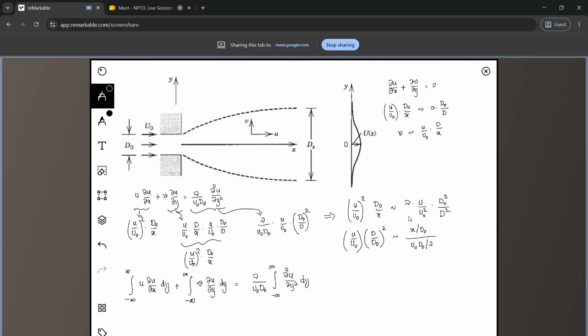Because when you have a wall, we have tau wall. But now I'm saying that here we get maximum velocity, which means tau wall is 0. So if tau wall is 0, then we do not have any equation at all from that. So which means something is getting conserved here. What is it that is getting conserved here? Like in the case of the flat plate that we were solving in lecture videos, there is a shear stress at the wall, because of which energy is getting continuously lost. But here we do not have anything like that. So something is getting conserved here.